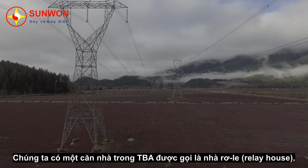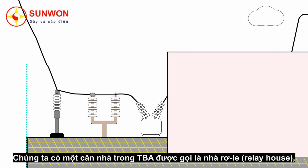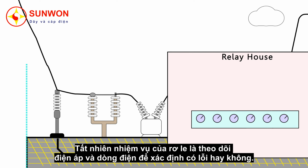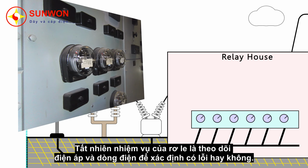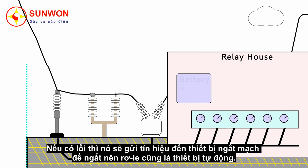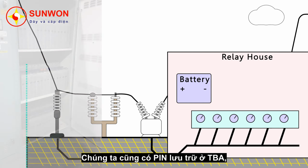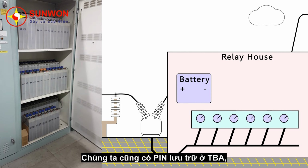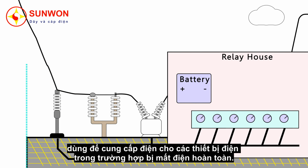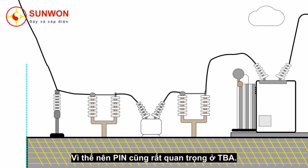We also have in a substation a building called the relay house. And as the name suggests, this is home to the relays. Of course, the job of the relay is to monitor the voltage and current and make a decision on whether there's a fault. If there is a fault, it will send the signal to the circuit breaker to trip. So the relay is an automated way to do this. We also have the battery. The battery in the substation is a way to power the equipment if you get a complete power outage. So really important. The battery is so important in a substation.